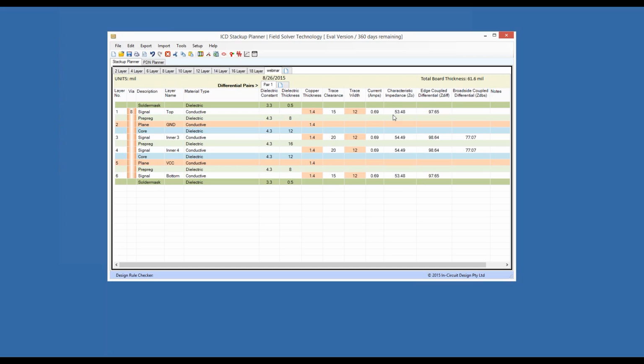But the problem is that you got to understand that in fabrication and manufacturing, there are tolerances that you're dealing with. So even if you got this thing to look pristine at 50, you're kind of wasting your time. You want to get in the ballpark, okay, but there's going to be tolerances there. So you got to remember that no 2 materials are ever made the exact same way. No 2 processes are done the exact same way. No 2 people work the same way. No 2 fabrication companies work the same way. So as a result of that, you're going to get close to 50, but you're not going to get it